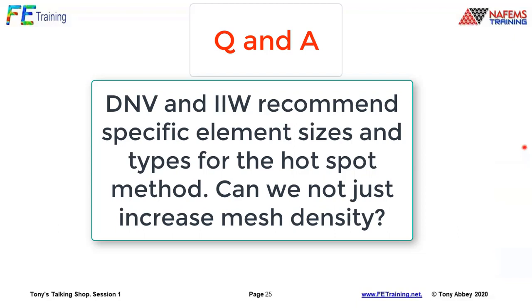quite critical. These days, what I would say is I tend to just saturate the mesh, look at the stress distribution curves as I've done, and then extrapolate using either eyeball or some sort of more formal method, from zone 2, zone 3, zone 2 into zone 1. I don't think we'd be restricted these days to the very formulaic distances that are recommended by those guys. I think that harks back to the old days, as I said, with very coarse meshes.